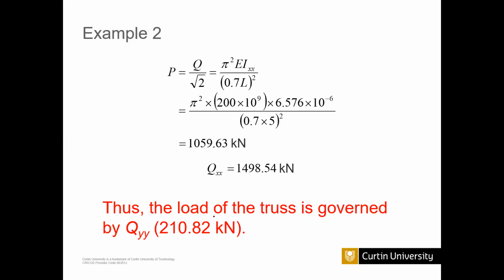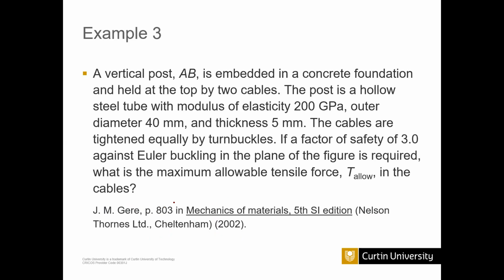So that truss will easily fail in the YY direction. So that means you need to consider the YY direction, I mean the YY axis, rather than the X axis when you apply the load on that particular structure. So that is the comment.